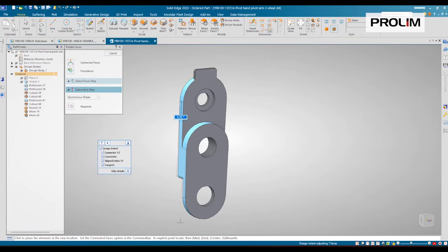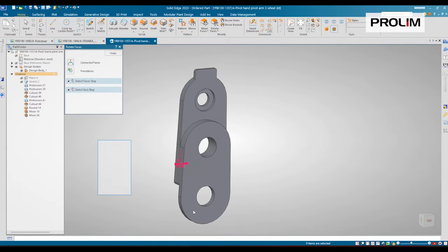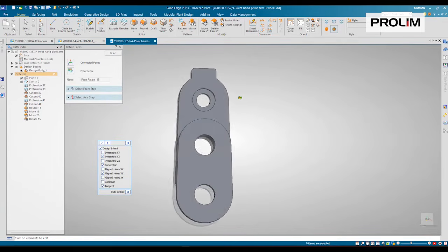So I want to actually add in a little change here to this original base plate of the part. And again, in a traditional ordered environment, we would have to go back and change the sketch and then update any preceding features if they somehow became unattached or errored out for us. So we can do this on the fly here, and as you can see pretty easily, I'm just going to make this a -2 degree change here. And there we go. And just like that, we have a pretty cool finished part.